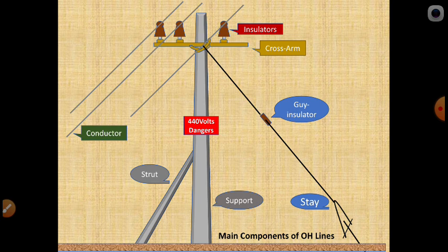Not only this, we can place different components also. What are the main components? Barbed wiring we require at some crossings, road crossing, and at railway track crossing we require V guards, and guarding requirements. RYB phase plates are required, danger plates are required.